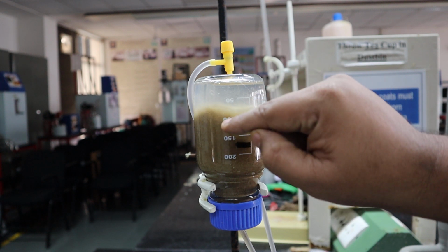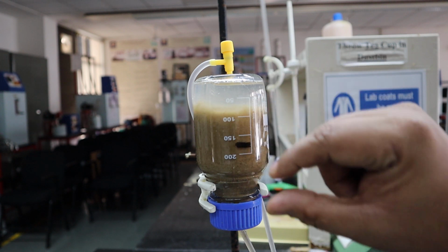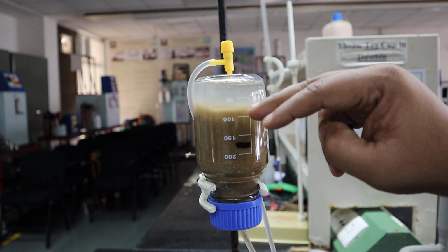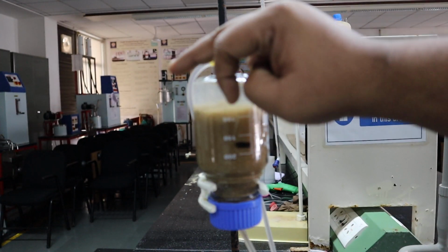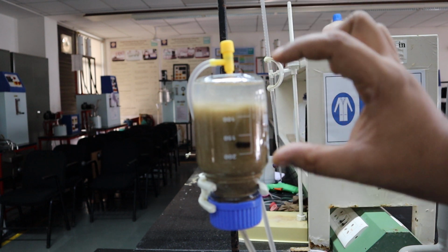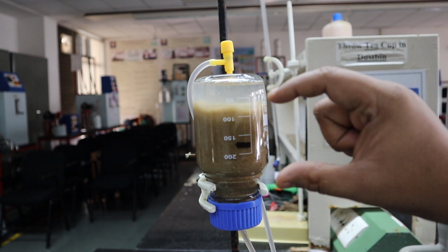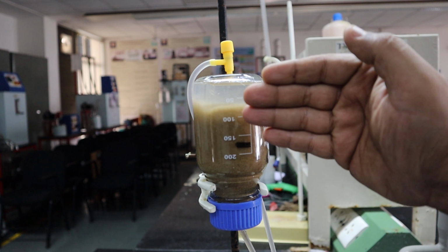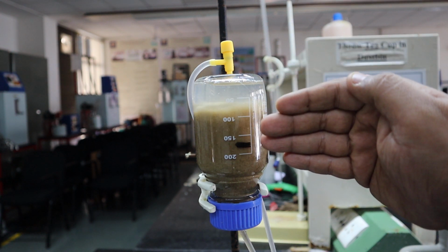You also get more surface area, because the particles get separated, so more surface area will be available. If you keep a velocity higher than the fluidization velocity, what happens? The particles will go to the outlet. I have maintained a certain velocity so that the entire bed is in the fluidized condition. Because of this, you can transport solids. Beyond fluidization, that is called pneumatic or hydraulic conveying.